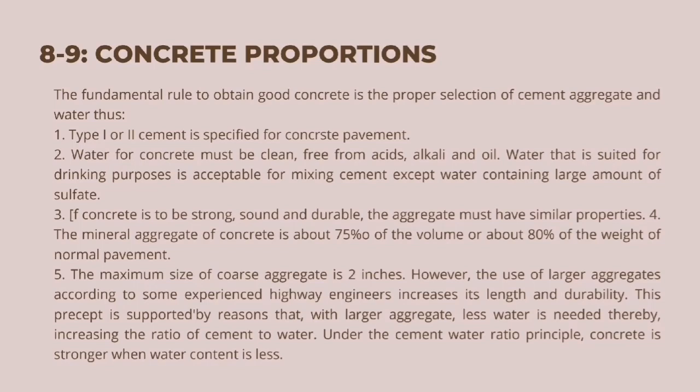However, the use of larger aggregates, according to some experienced highway engineers, increases its strength and durability. This precept is supported by the reason that with larger aggregate, less water is needed, thereby increasing the ratio of cement to water. Under the cement-water ratio principle, concrete is stronger when water content is less.